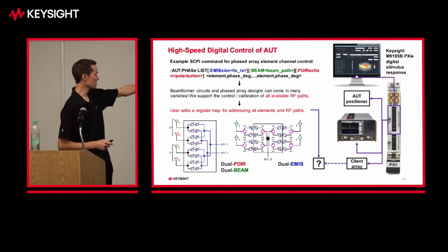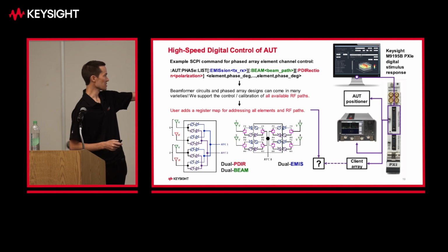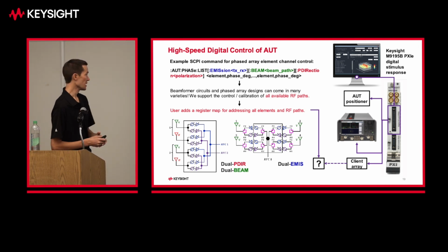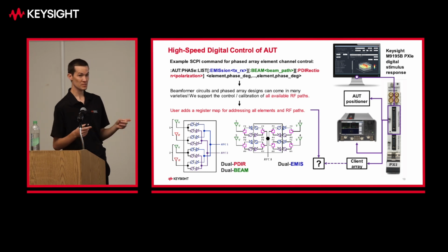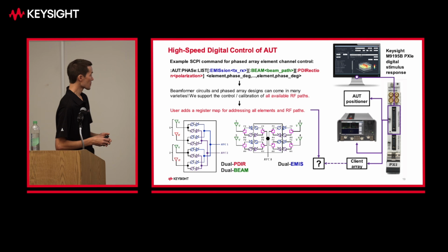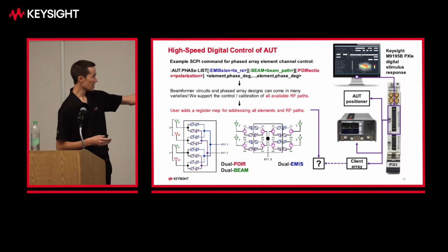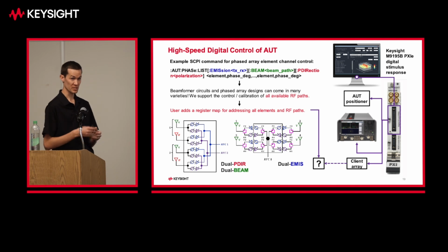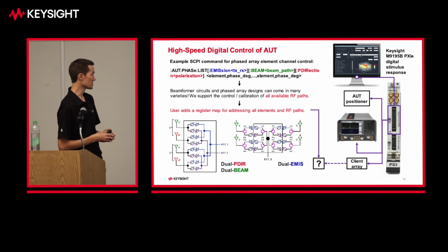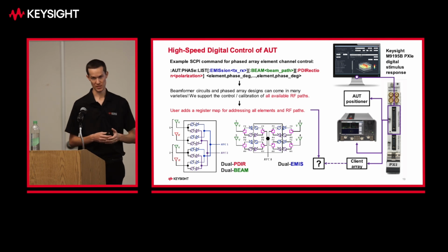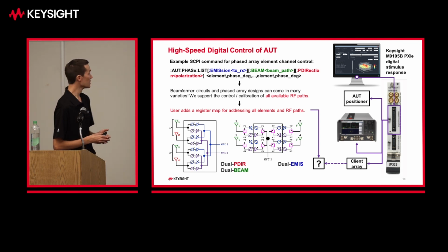On the left here, you see an example of a beamforming IC that's connected to dual polarized feed antennas and has two separate beams on two separate Wilkinson power dividers that are routed through the IC. And on the right-hand side, you can see another example of a beamforming IC that is both transmit and receive, so you have a switch path. And in this case, it's single polarized, so you have 4 elements with a single feed point at each element.